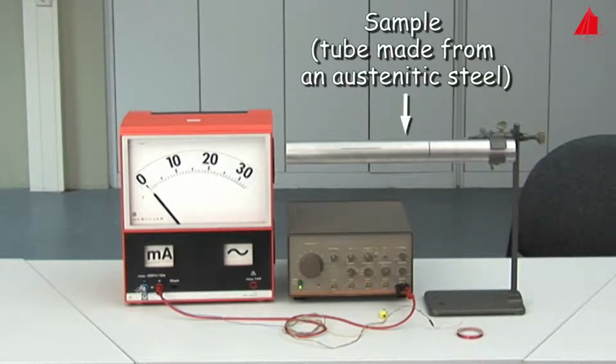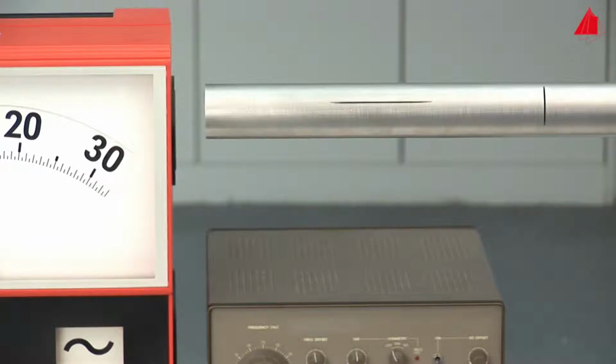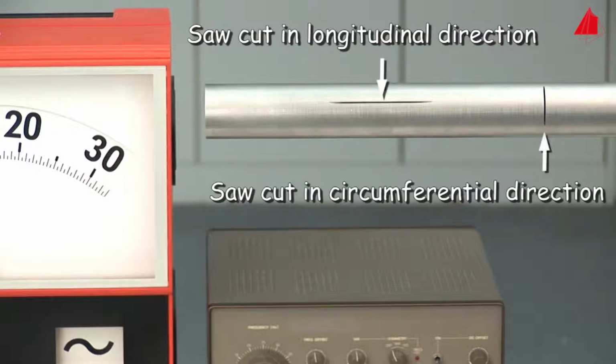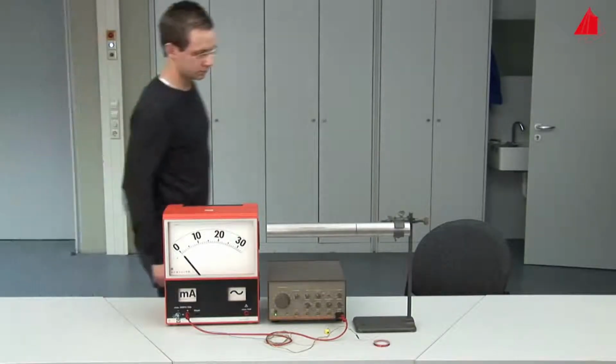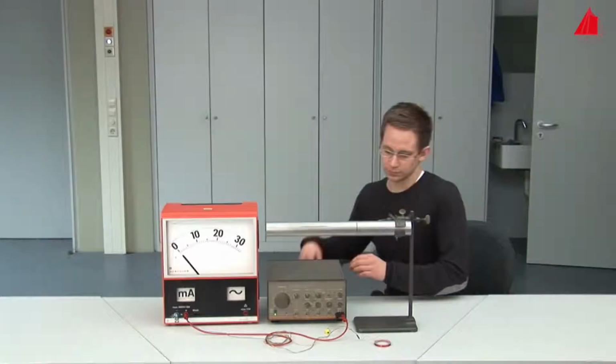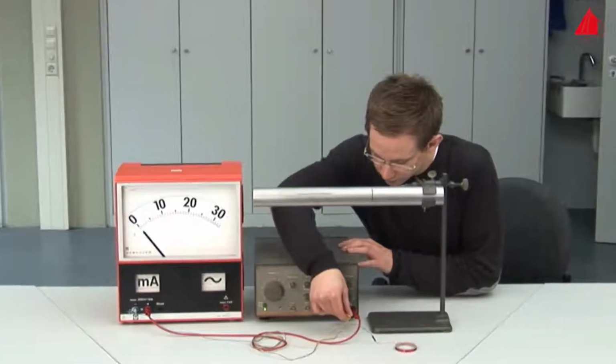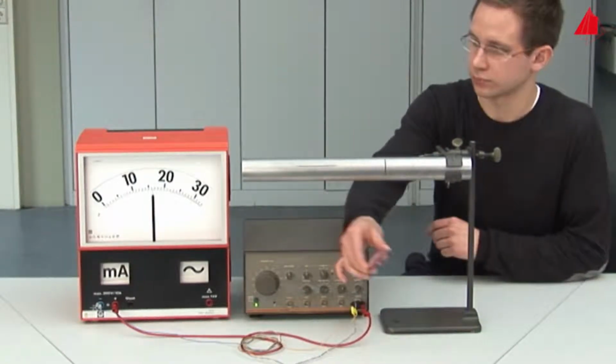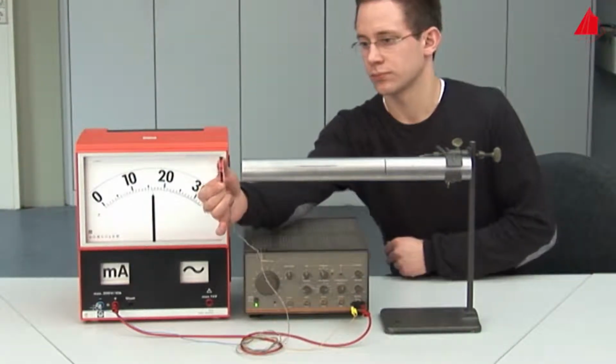Our sample is a tube made from an austenitic non-magnetic steel. We have purposely machined two cuts through the tube wall, one in longitudinal direction and one in circumferential direction. And here we go. The materials tester connects the return cable to the alternating voltage source. This closes the electrical circuit. The current consumption of the coil is still relatively low.